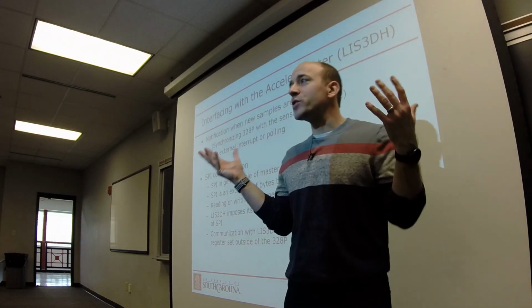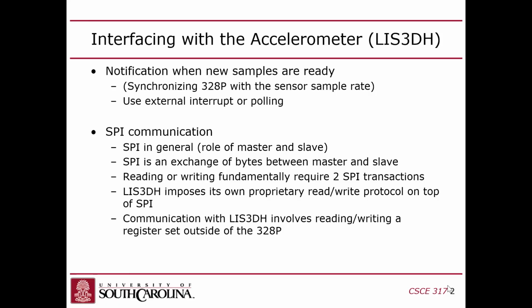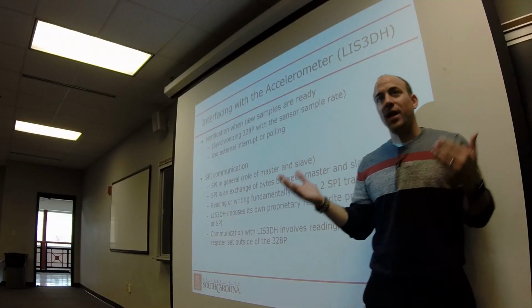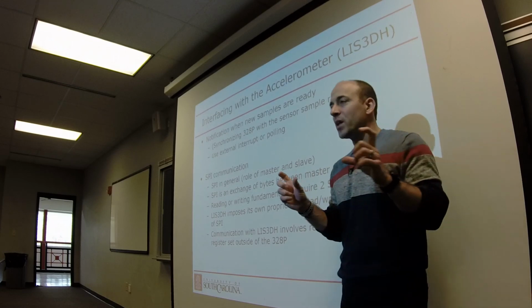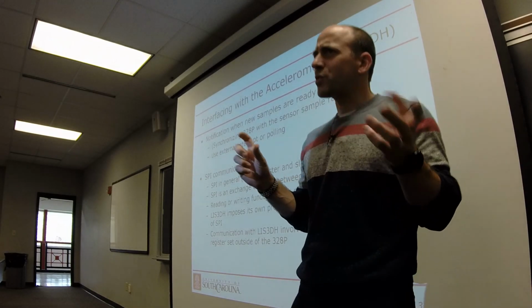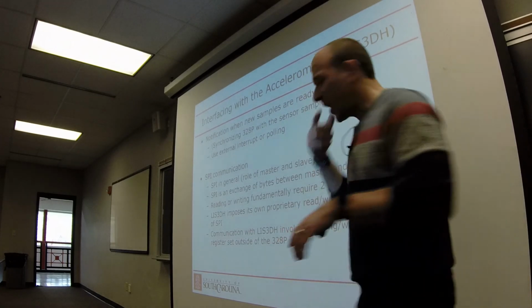Okay, so what's the point? You have to know a little bit about SPI to use SPI. Even though SPI is being physically implemented in hardware, you have to understand what's going on in order to use even the hardware, right? You have to understand the notion that there's this slave select and that there's an exchange happening. And then on top of that, you have to understand the specific protocol that the LIS3, is that what it's called? LIS3 is expecting, right?